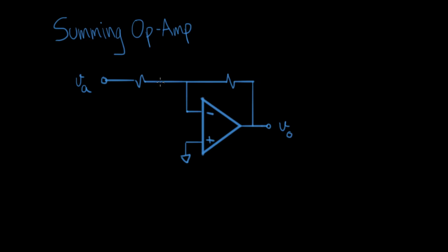different kind of circuit. So I'm going to add another resistor right here, like this, and a second input. We'll call this VB. And so we'll have RA here. This will be RB. And we'll call this R feedback. And the question again is now, what is V out in terms of the inputs, VA and VB? We're going to use the idea of a virtual ground.